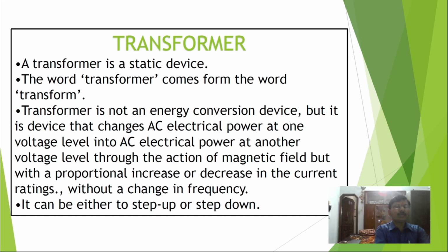Transformer. A transformer is a static device. The word transformer comes from the word transform. Transformer is not an energy conversion device, but it is a device that changes AC electrical power at one voltage level into AC electrical power at another voltage level through the action of magnetic field, but with a proportional increase or decrease in the current ratings without a change in frequency. It can be either to step up or step down.